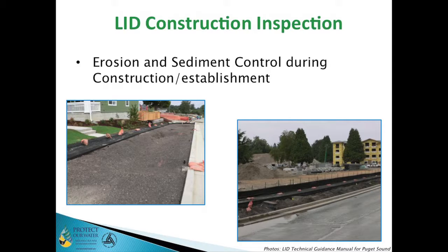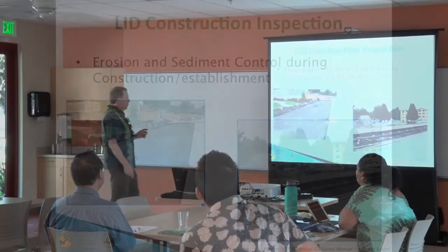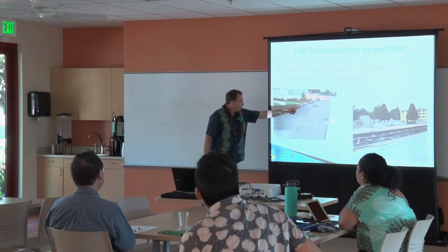Erosion and sediment control during construction, or more importantly during establishment. One of the most common problems we have during construction of LID is what I mentioned earlier. We build the LID device and then we get construction sediment from another part of the project flood in there and plug up all this nice bioinfiltration soil that we put in there. And really the only way to fix that is to go in and dig the whole thing out and start over and rebuild it.